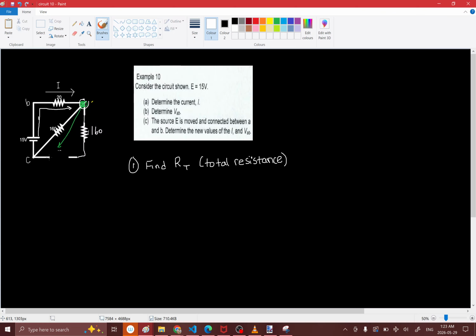And okay, so that old resistor is going to be replaced here with a wire. So let's look at the circuit again. We have current coming out like this. It goes over like that, hits this node, and then goes through here and goes through here. So that means that the 160 ohm resistor here is actually in parallel with this 160 ohm resistor. So if they're in parallel, that means that you can just slap them together.